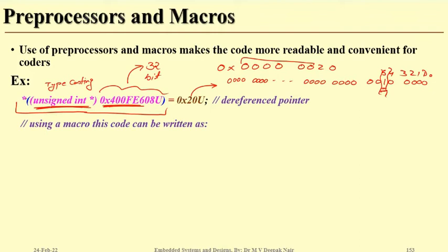Now second, there is a star in front of the address. If you put a star, what does that mean? It is a pointer to that address, and we are going to dereference the register with the data. Dereferencing means entering the value into that pointer or that address. There can be many methods to enter a value into this address, but this is the safest approach which C provides: pointers, typecasting, and then the data. So now this data will be entered into this register, and it will enable the clock of port F.